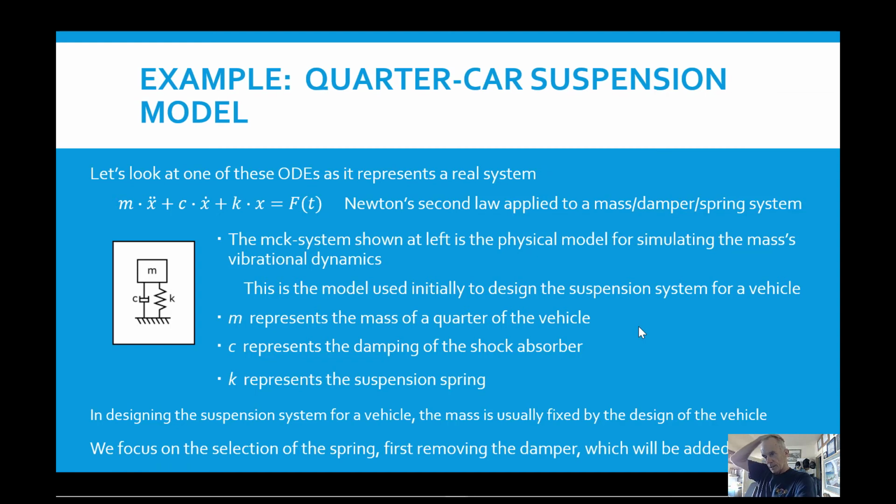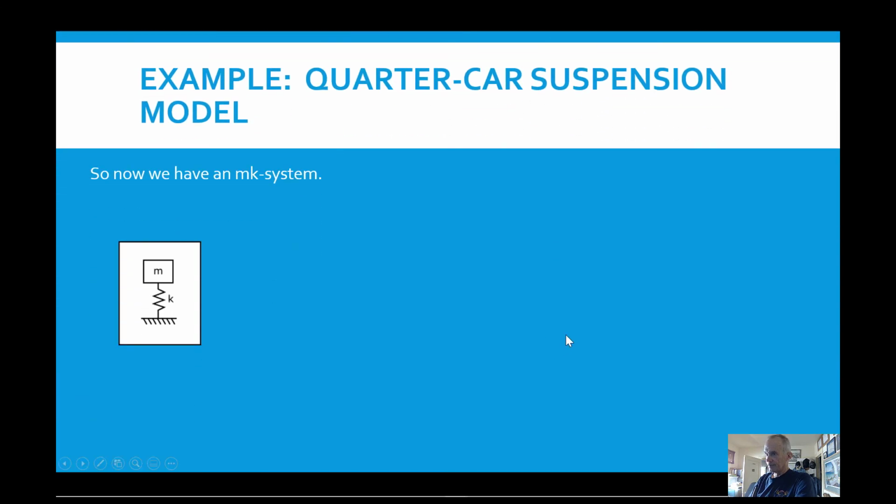We don't design the shock absorber and the spring at the same time. We take the shock absorber away and focus on the spring to start out with, and then we add the shock absorber. The shock absorber is sort of an afterthought in a way. The first thing to do is focus on designing the spring.